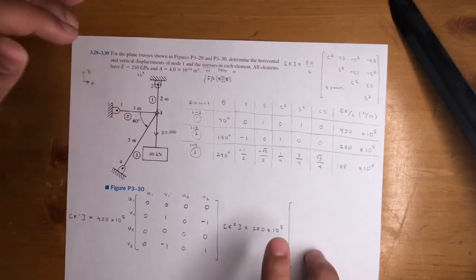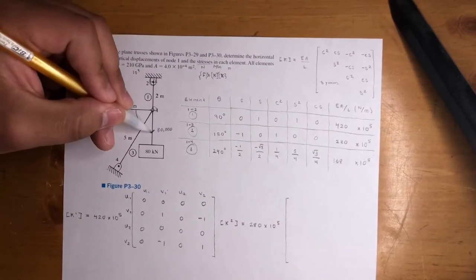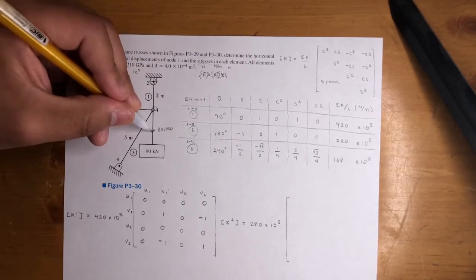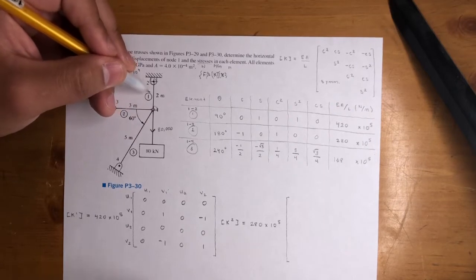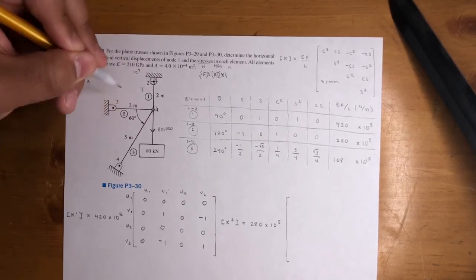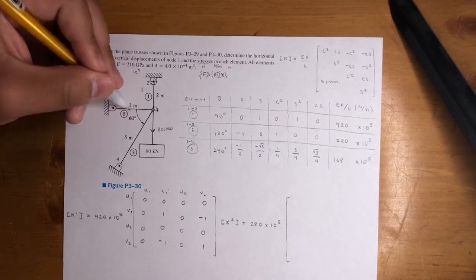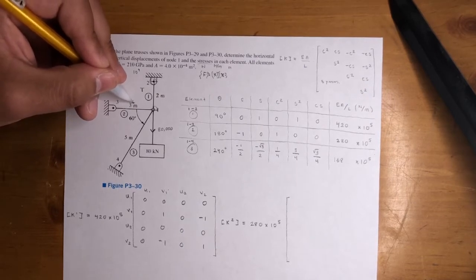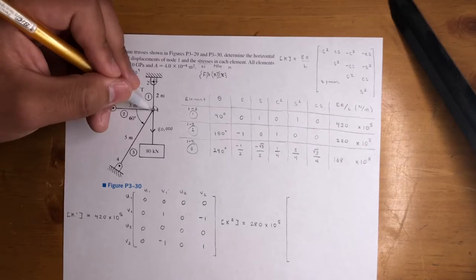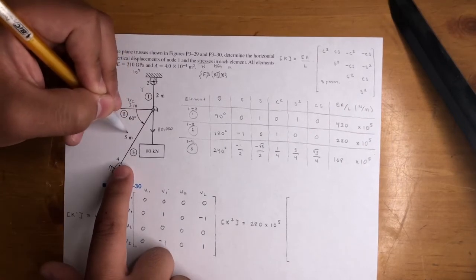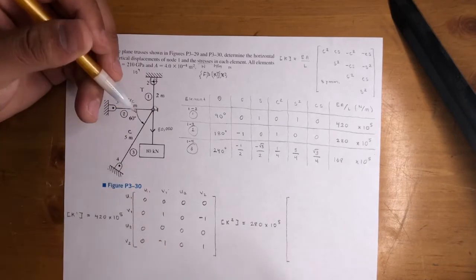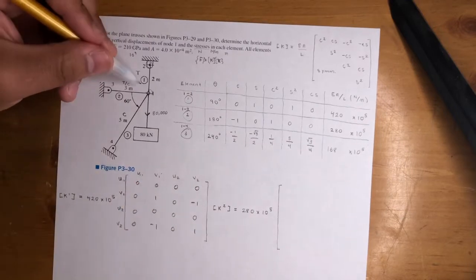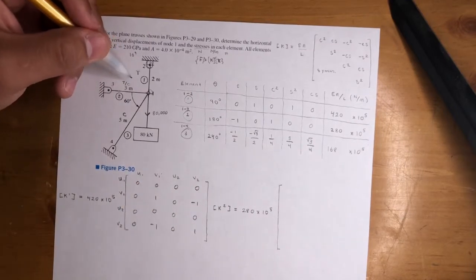And just hold on before we continue. Just by looking at this, don't think of it logically. It's not engineering, it's just logic. If you pull this down, this bar is going to be in tension, right? You're stretching it. So this one's tension. This one, you really can't tell. Tension or compression, who knows? Let's just keep it tension or compression for now. And this one, if you push it down, you're kind of compressing it, okay? So this one's going to be in compression, I'm assuming. Well, I already know because I already did the problem, but even before I started this problem, I made the same assumptions. That's just looking at it logically, okay? So just keep that in mind.